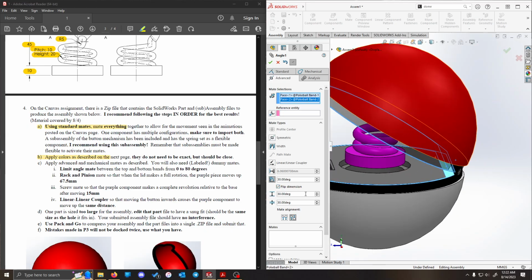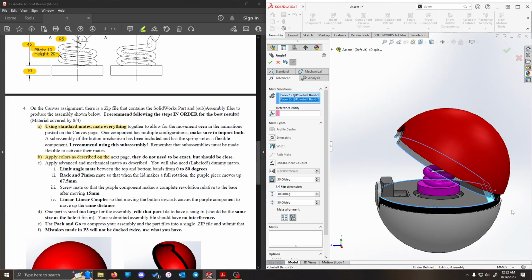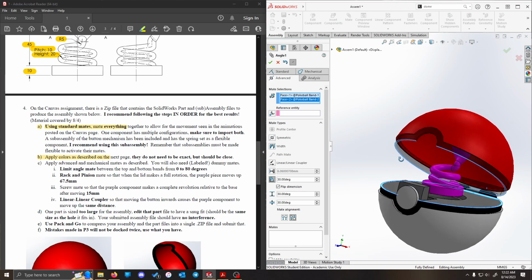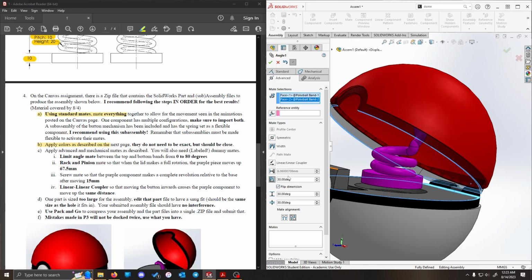I never actually know which ones are going to do which, but there's a total of 4 combinations between checked and unchecked and the mate alignment, so you can brute force your way through it and get the answer much faster than you could if you actually tried to think it out. So always remember, when there's a limited number of options, brute force is a perfectly valid method of going through it. So we want the minimum angle to be 0.